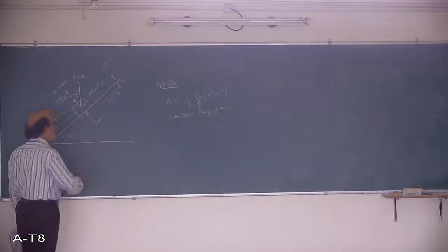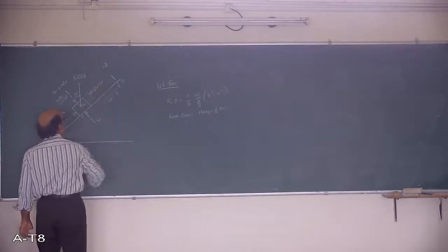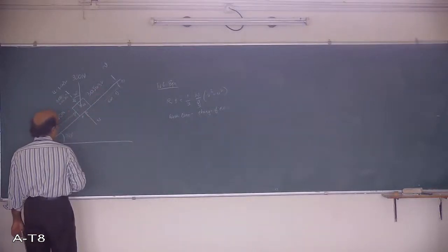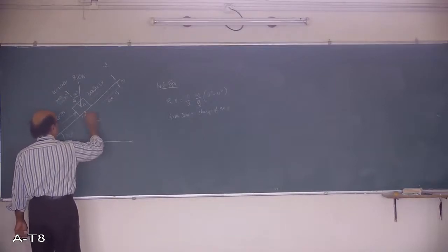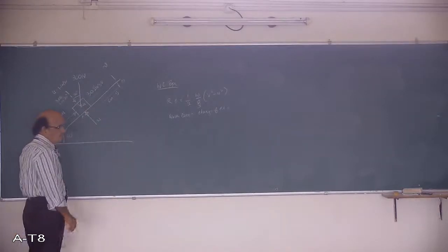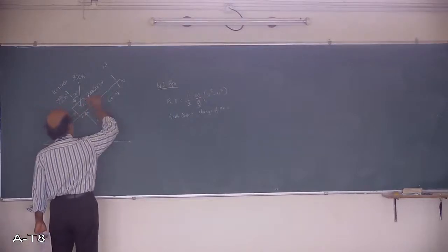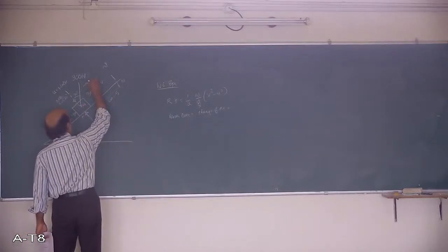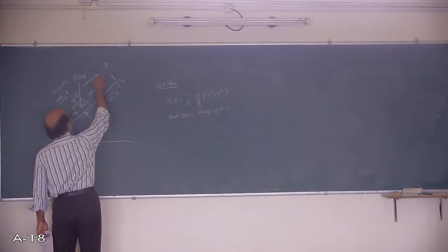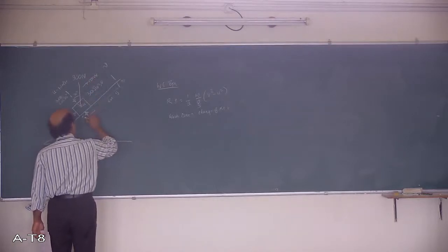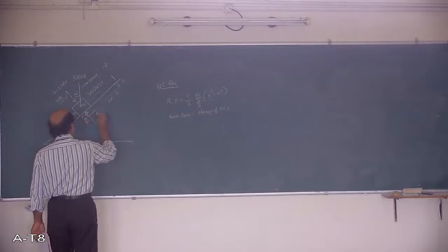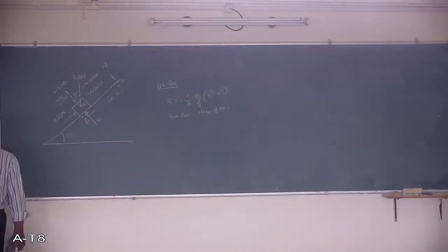The reaction N is acting upwards, and as the block is moving in this direction, the frictional force will act opposite to that. If you draw this free body diagram, 50% of the problem will be solved.